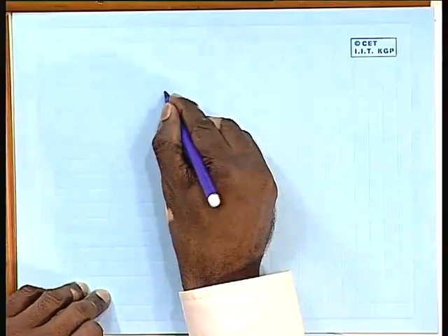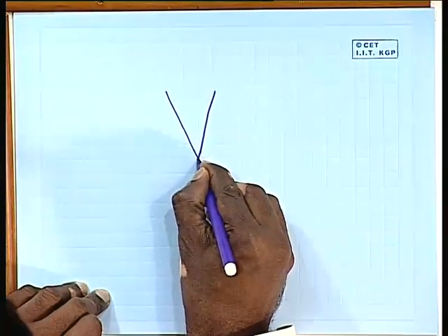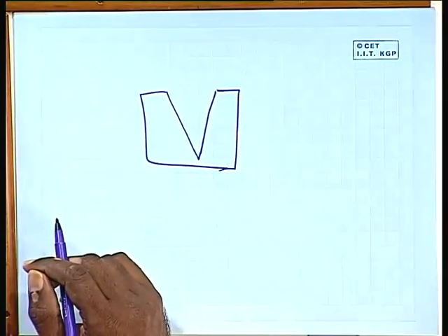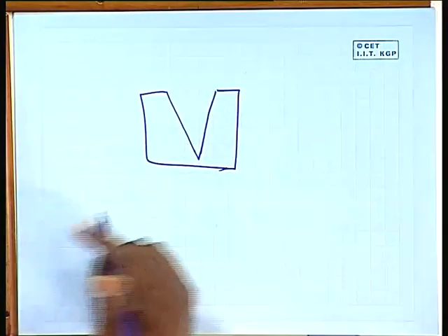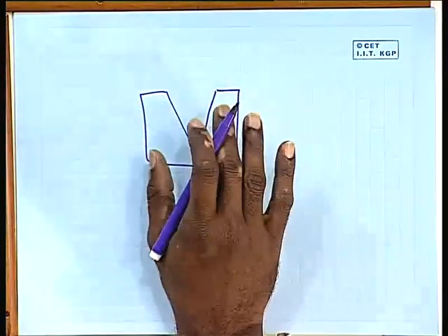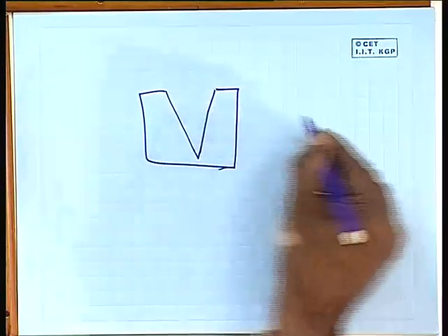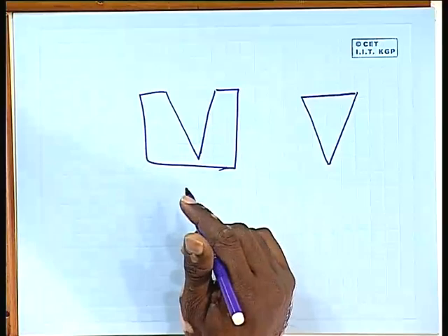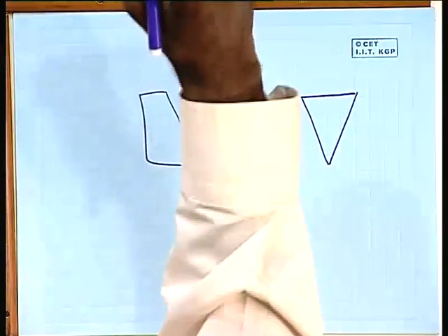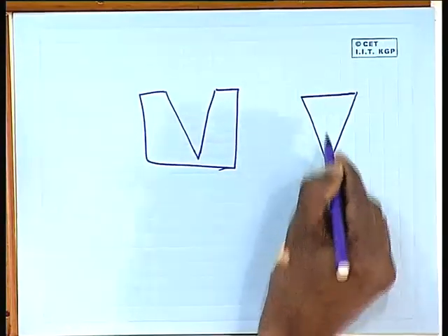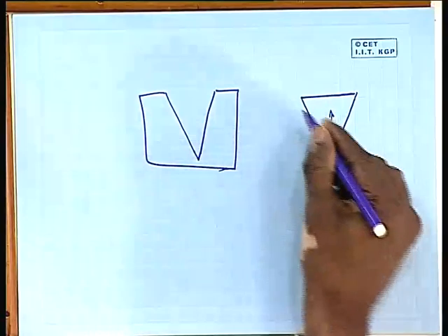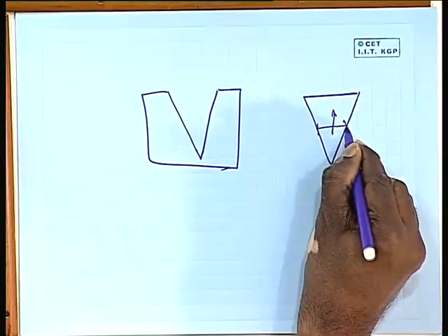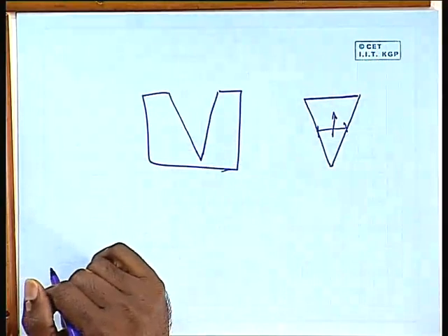Nowadays what people do is take a liquid and pour it into a tapered copper mold like this. Once it is solidified, you take that casting of this shape, section it vertically, and look at the structure from the tip upwards. You see the distance, or the diameter, up to which it is completely amorphous, beyond which some crystals start forming.